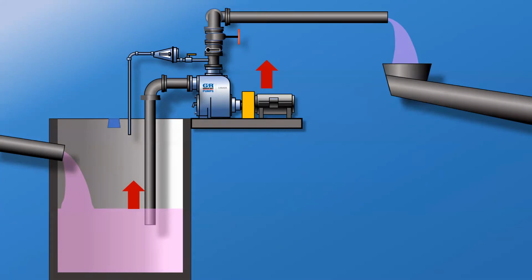And if we do catch up on this, and we find that, hey, we are starting to now bring down the level in the wet well, well, let's slow down the VFD, and therefore slow down the motor. And therefore we're keeping that wet well consistent, and hopefully keeping a more consistent flow that's going to whatever the process is down the line. In this case, it would be a treatment plant. Adrian, you have anything to add in this case?